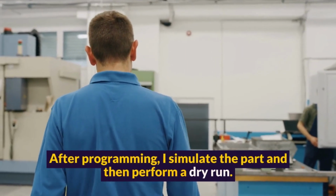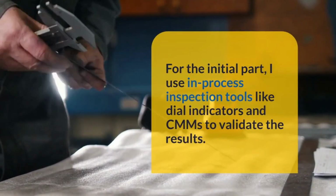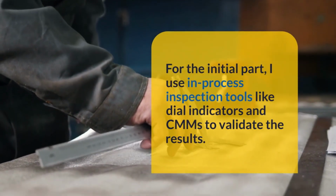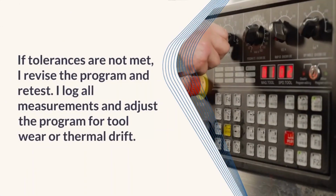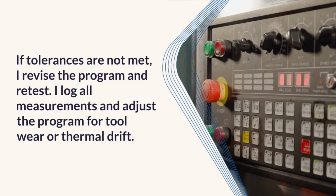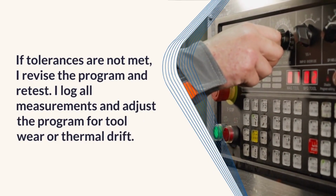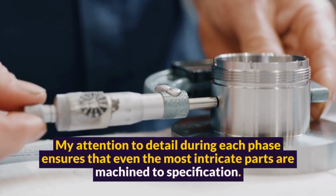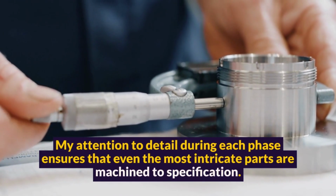After programming, I simulate the part and then perform a dry run. For the initial part, I use in-process inspection tools like dial indicators and CMMs to validate the results. If tolerances are not met, I revise the program and retest. I log all measurements and adjust the program for tool wear or thermal drift. My attention to detail during each phase ensures that even the most intricate parts are machined to specification.